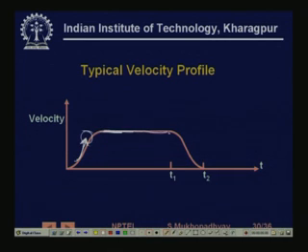So the velocity is maintained, and then towards the end, as the position error reduces, the reference pulses will actually stop coming. Their frequency will be reduced. So now there will be more encoder pulses, so the counter value will also come down, and towards the end it will become 0, and at that time the motor will stop.